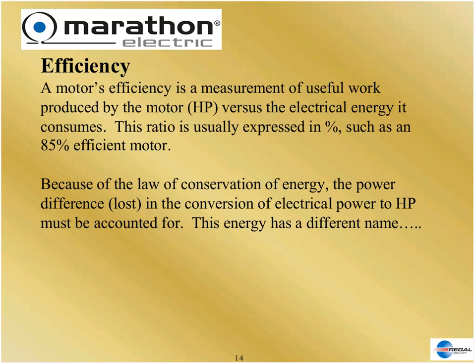Okay, so now we're going to take the electrical power from the utility, we're going to capture it into our motor, we're going to get our rotor to rotate, we're going to hook a load to it, and we're going to make horsepower. There is no possible way, unless you defy the laws of physics, to make the horsepower value be exactly equal to the input value supplied by the utility. There's always some loss. The ratio between the work done and the work in is expressed as a fraction, which we usually use as a percent, and that is called efficiency. How well does the motor do this conversion?